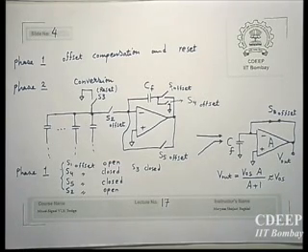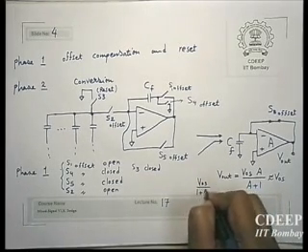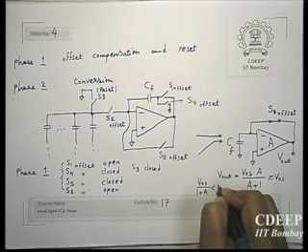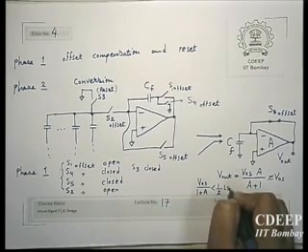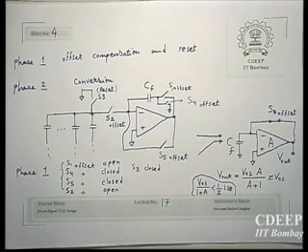So we will use a very high gain op-amp so that we will get almost V offset. In fact, the error is V offset upon (1 plus A). We want to make it small enough compared to half LSB. This is the first condition for the gain of the op-amp. And then we make it small enough so that eventually the offset will get compensated.